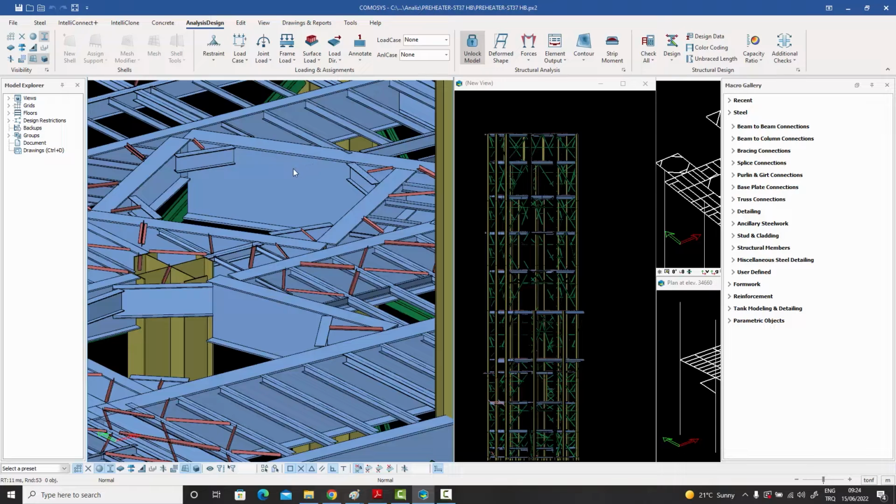But what I really wanted to say was that you want to transfer your forces from your load combinations into the beam first, and then look at those forces and see if they're extremely low. They could be as low as 0.05, or 5% of the shear capacity. In those cases, you want to increase that number to some sort of a minimum, say of the order of half the capacity, or 0.4 of the capacity or something like that.